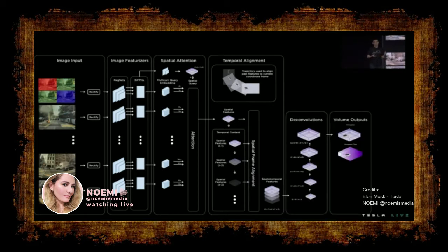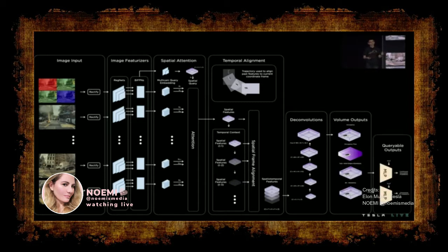Next, these spatial temporal features go through a set of deconvolutions to produce the final occupancy and occupancy flow output. They're formed as a fixed-size voxel grid, which might not be precise enough for planning and control. In order to get a higher resolution, we also produce per-voxel feature maps, which we feed into an MLP with 3D spatial point queries to get position and semantics at any arbitrary location.